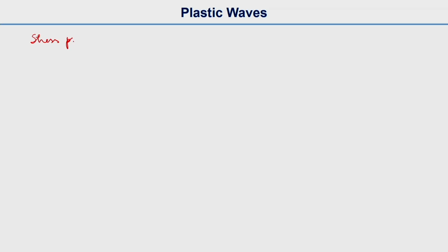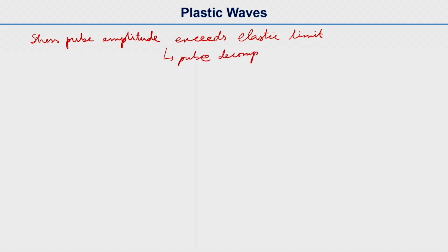So when the stress pulse amplitude exceeds the elastic limit, the pulse will decompose into an elastic wave and a plastic wave.